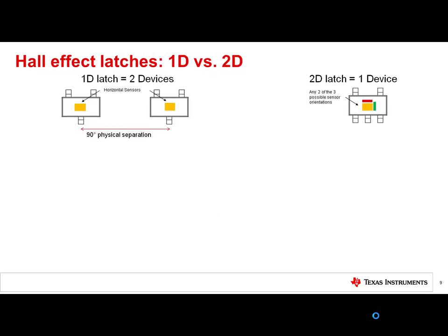Again, 1-dimensional Hall effect sensors require the 2 devices to be spaced such that the outputs are electrically 90 degrees apart. Here we can observe both the direction and speed of the rotating magnet based on the frequency of pulses and the order of rising and falling edges.